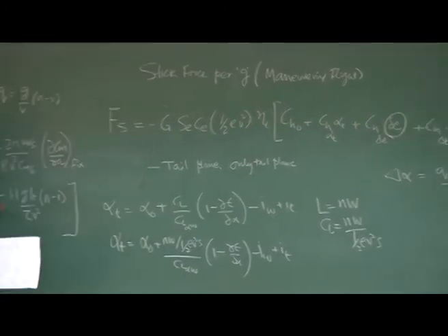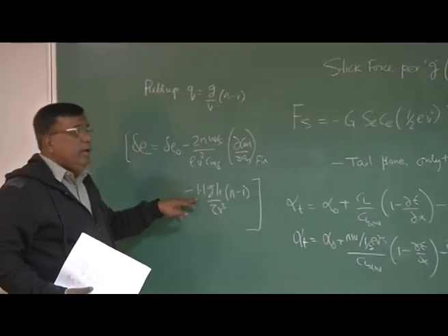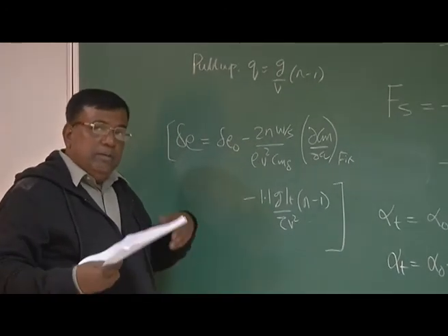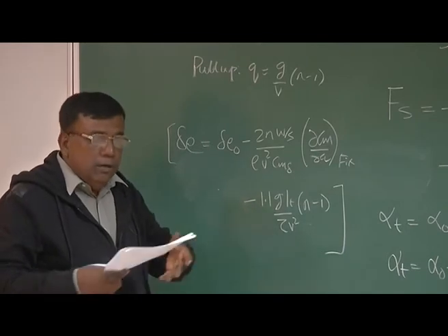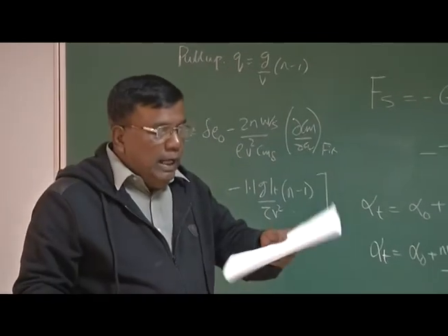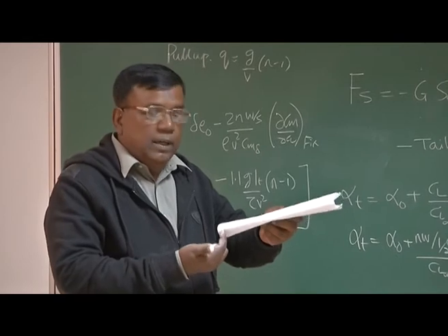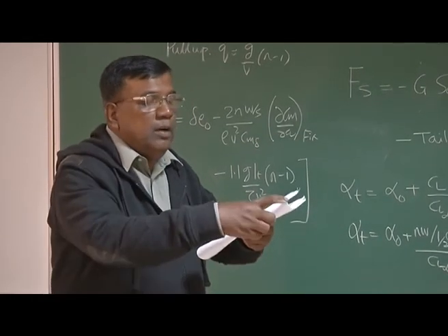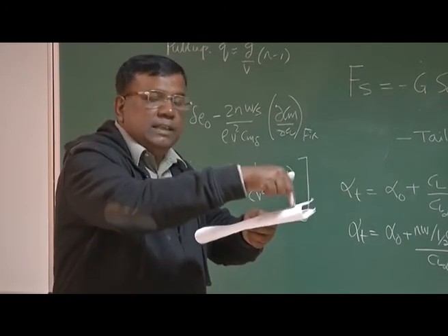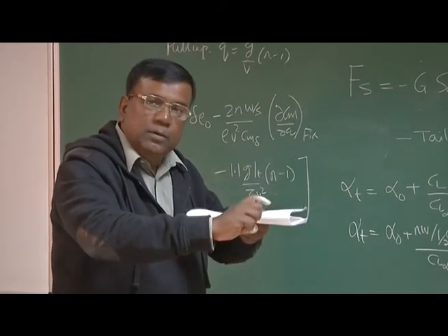This 1.1 came here because we are talking about the damping effect because of the portion ahead of the wing quarter chord, right? What actually happens, as I am going like this, there is an increment in angle of attack here, so it gives stability. As this front portion goes up, there is a relative air like this, so they also try to discourage it and give a nose down moment.